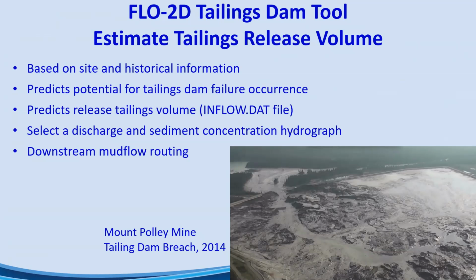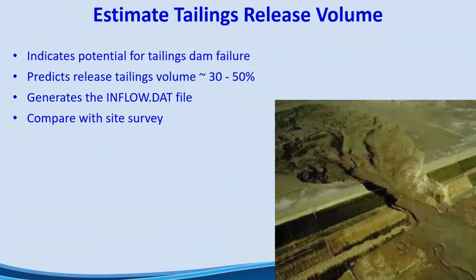In the tool you will also need to select a discharge and a sediment concentration hydrograph, and we will use some typical hydrographs to distribute that release volume, and you will see that in a minute. Then we use the FLO-2D model to route the mudflow downstream.